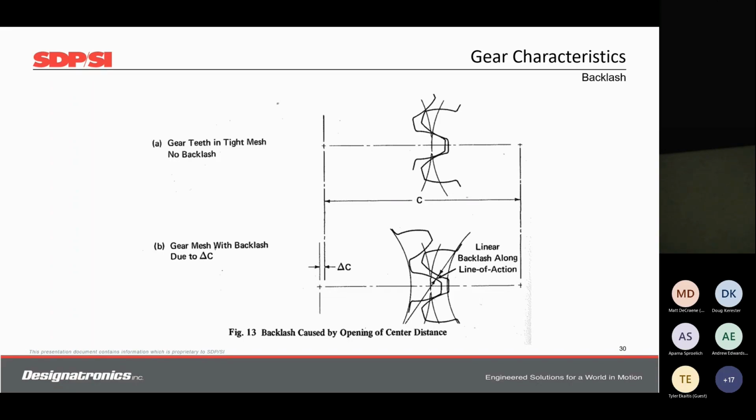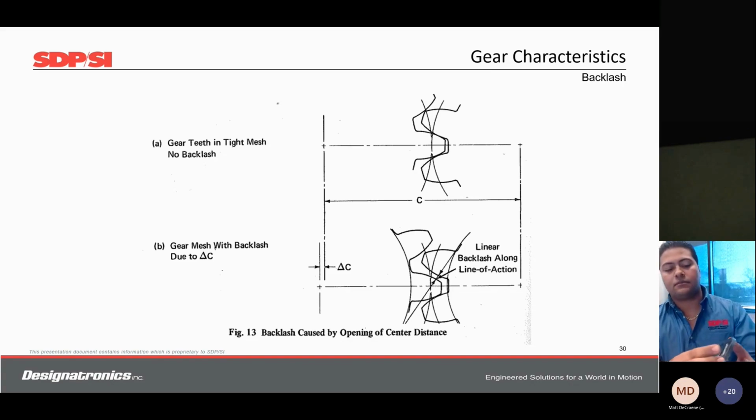We do offer anti-backlash gears, which produce zero backlash. It's a special design where gear teeth are spring-loaded, so the gap is closed, but motion still occurs. This motion occurs due to the preload in the springs. I have a sample here of an anti-backlash gear. The anti-backlash gear is preloaded like this. You can see how the springs stretch. This is inserted into the mechanism, and it'll allow for motion with zero backlash.